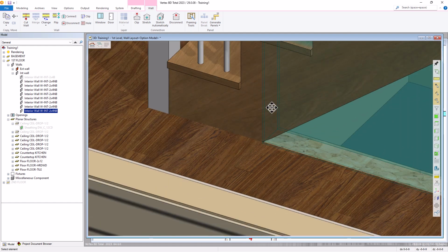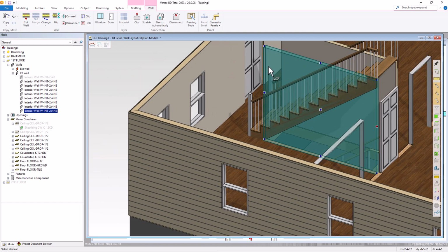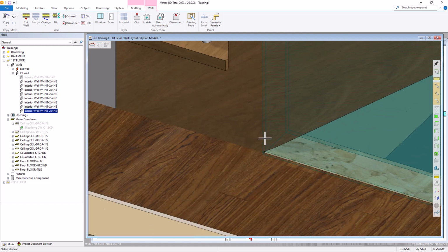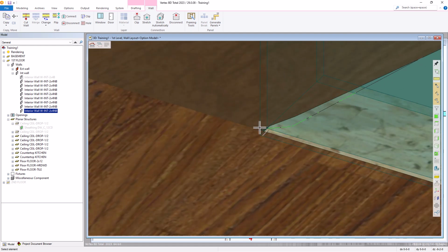I'm going to zoom back out. This time I'm going to select the top upper left grip point. Press the O key to lock it in the Z-axis. And come down and find a vertical point right above that point. You can see that our dash line again has adjusted. So we found the intersection point. So we'll left click. So it just steps up. I think that's the difference of the hardwood thickness.